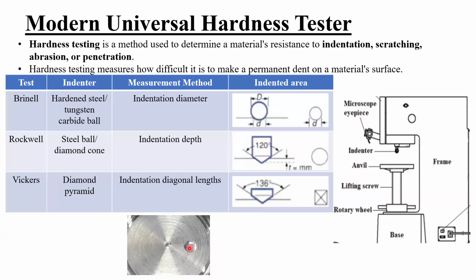For your hardness testing, you can use whatever materials you require, but preferably not things like rubber or plastic materials. You cannot use them because they have the highest elasticity, and the material will return to the same position once the indenter is taken out of it. So this is preferably used for your steel, iron, or metal items.